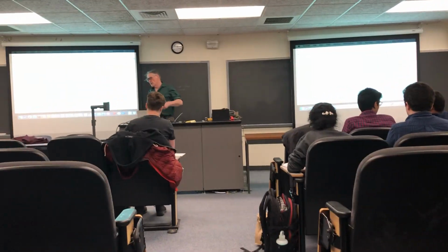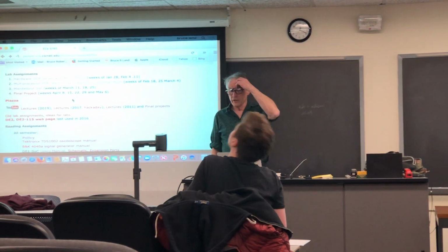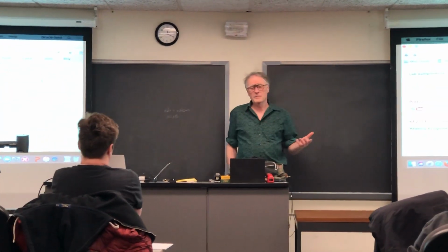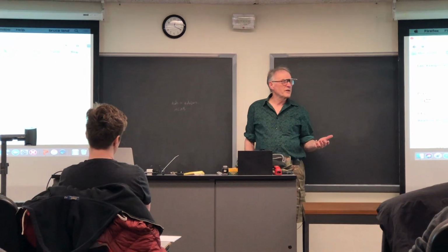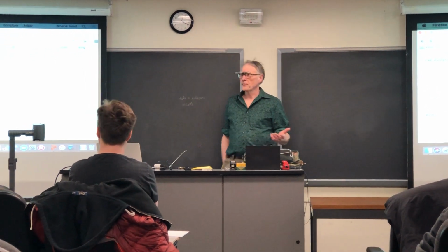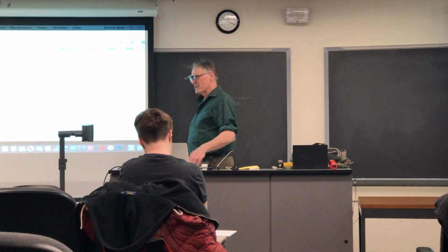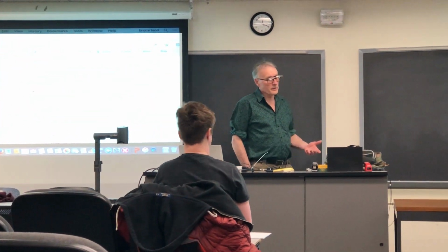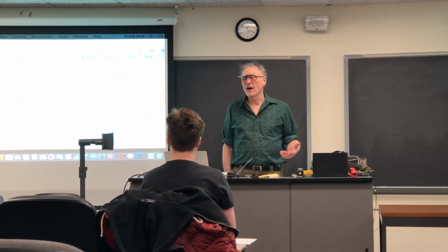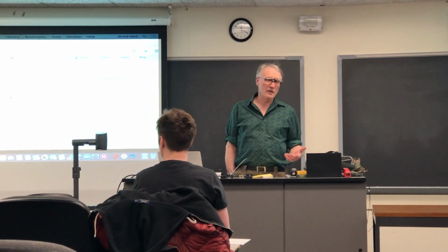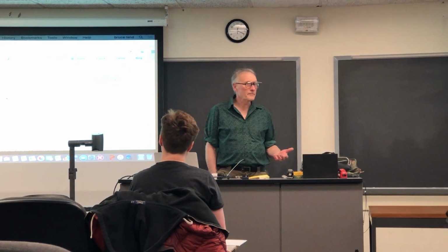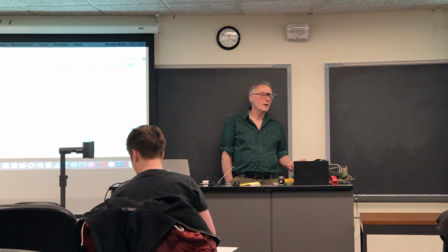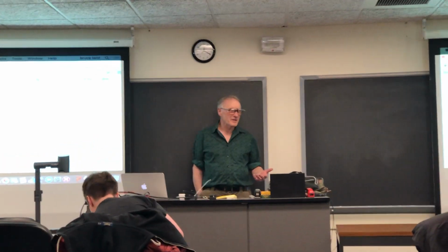Okay. So one thing you're going to run into with Lab 2 when you start building big systems is the compile times. Actually, the fitter phase is going to take a long time. And there's a couple of things to do. One is, of course, make sure that you're not trying to allocate 105% of the logic elements, because the fitter will try, and it's stupid, and then ultimately fail. But it takes a long time to decide you can't fit.